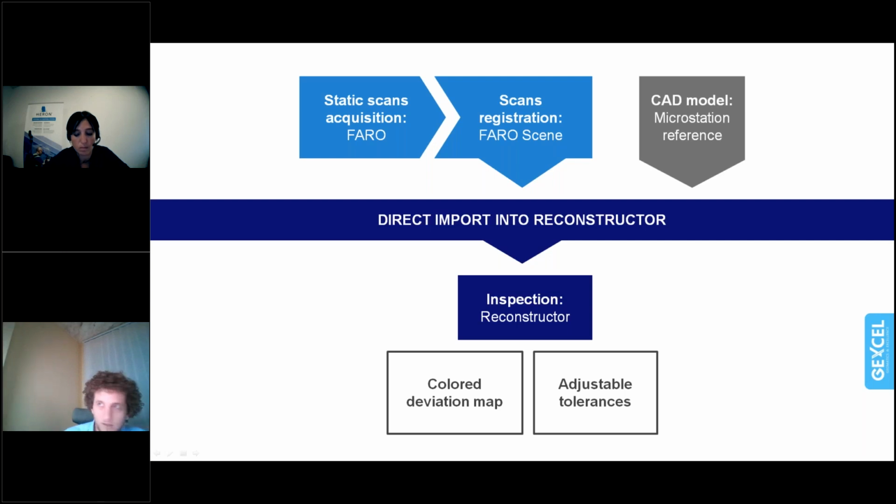We did about 20 scans inside. It was a two-level structure because in this kind of tank there is a floating panel inside, which is also important because we must check if there is something on the cylinder surface which could interact with this floating panel, which can go up and down. So that's something like a red flag in this kind of project.